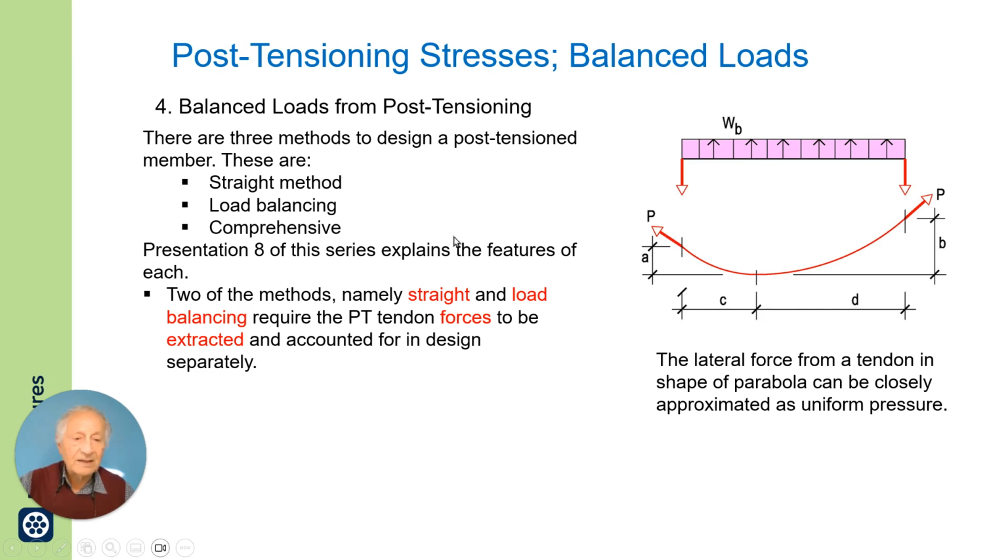Now, if you have a parabolic tendon, the lateral force from a tendon in the shape of a parabola can be closely approximated as a uniform load. A lot of engineers, in particular in the past, when computer applications were not common, used profiles for tendons consisting of parabolic segments so that the force would be uniform.